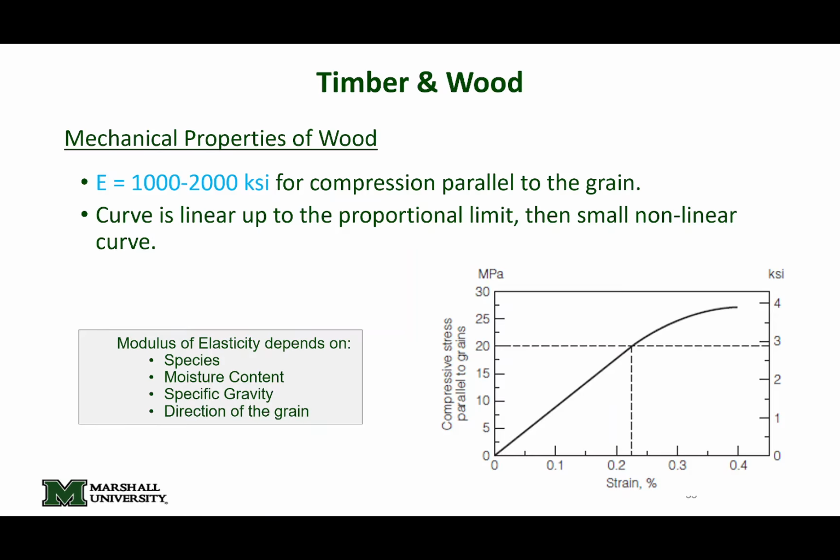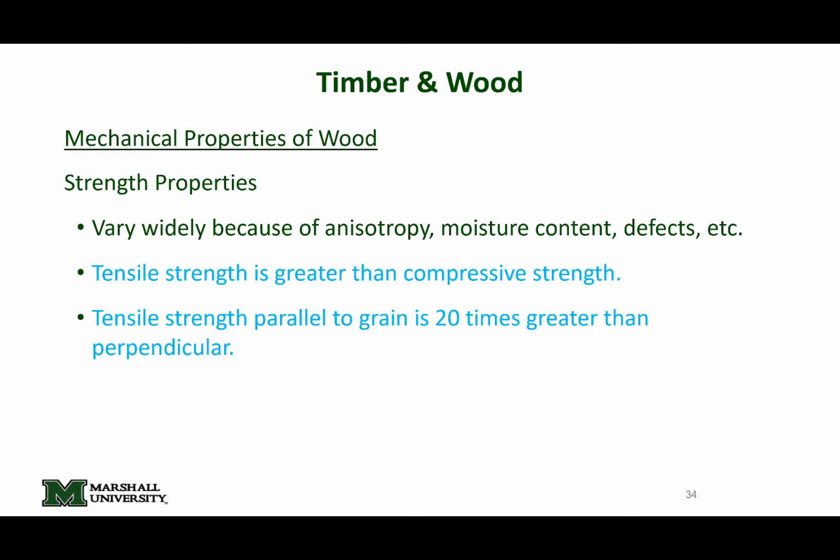So let's talk about some mechanical properties. What I have here is the Young's modulus of wood, and this is the one that we would use for serviceability computations. For stability computations, we reduce this a little bit. For regular old serviceability computations, Young's modulus for wood is somewhere between 1 million and 2 million psi, dependent upon the species and what have you. And we can test that using a lot of the different tests that we've used this entire semester.